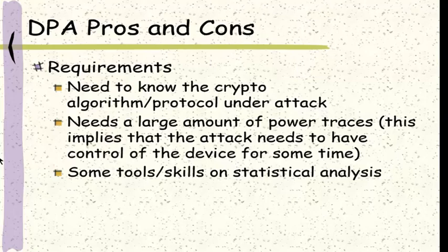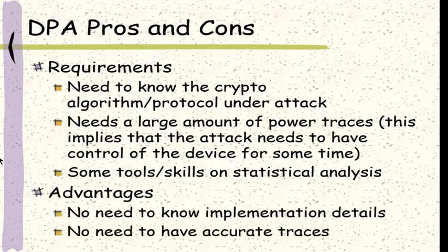Third, unlike the simple power analysis attacks that do not need much help from software tools, most of the differential power analysis attacks require some statistical analysis tools to study the data and extract the secret information. The two big advantages of differential power analysis attacks compared to simple power analysis are that they do not need to know the hardware and software implementation details of the crypto devices, and they do not need the power and the current waveforms to be very accurate either.